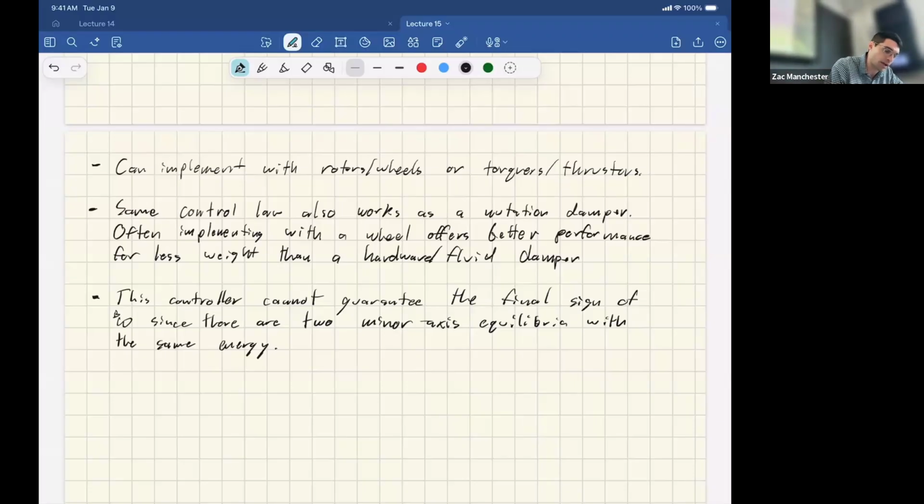I can summarize that whole expression into a nice little matrix. It gives me this torque. It's going to look like the following. So I'm going to have R1 cross A1, then R2 cross A2, dot, dot, dot, for all my thrusters, and then Rn cross An. So that's this term for each thruster. And I stack them in a matrix, and then I've got my vector over here of all the U's.